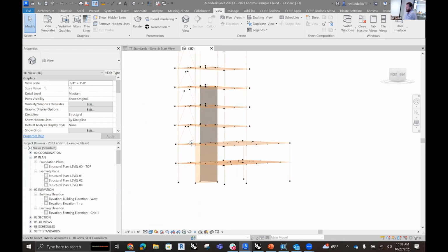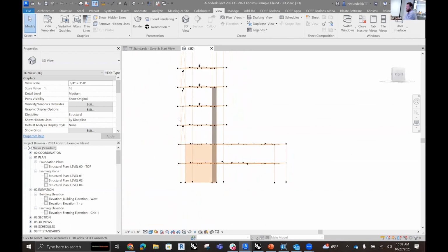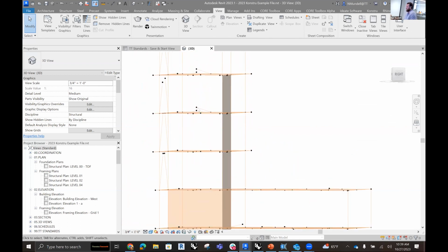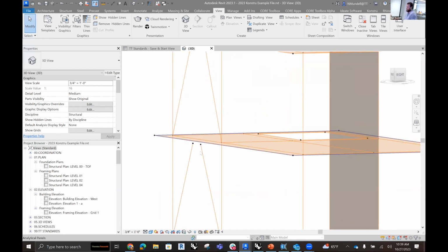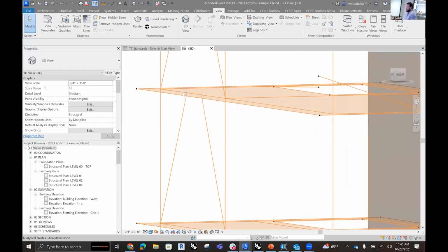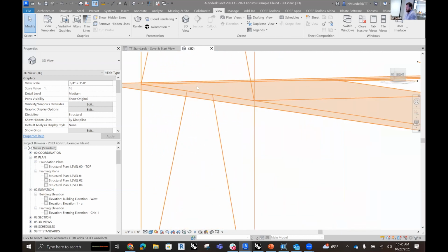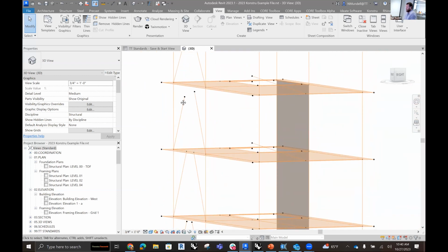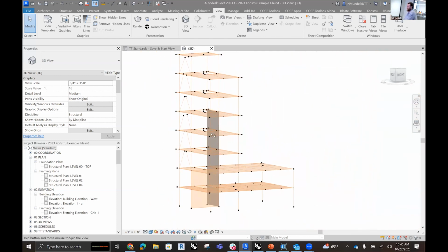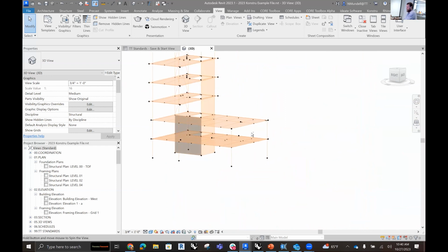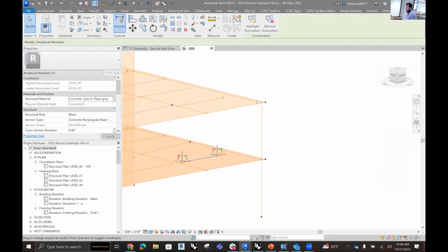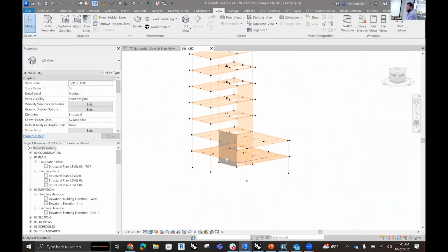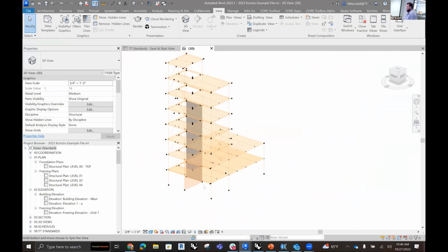And it should be pretty clear just from sort of zooming around the model that we have some issues here. First of all, we have some framing that is not planar, that is not connected to the level it's hosted by. As I said, we have a lot of braces in this model that are not fully connected to the beam position above where we want them to be. In this case, these are connected to the beam above, but what I really want is them to be all connected at the center, as a chevron brace should generally be. So issues with the model. We also have over here some sort of framing that's not extended. So this frame is far shorter than it should be to hit the edge of the slab. So multiple issues with the analytical geometry in this case.